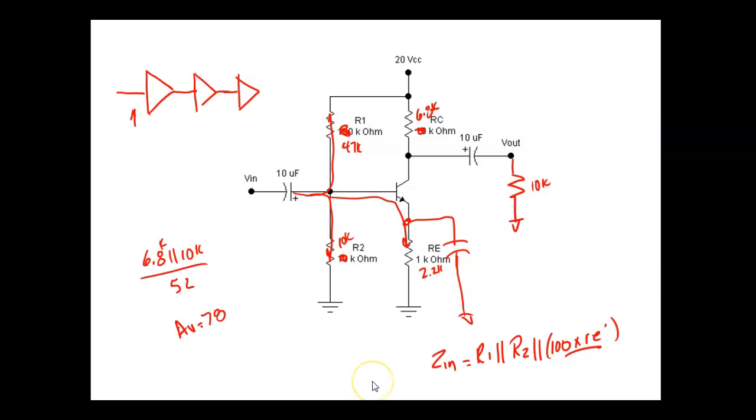So we should expect around what? 2,000? What y'all bet? What did we calculate? I need to write that down. 3189. So how am I going to measure that? Well, we can't measure that because that's a dynamic resistance. So if you disconnected everything and put your ohm meter on it, you're not going to measure anything, right? You understand that? So this is a dynamic resistance between the base and this right here. That only comes into play if you bias it with both.